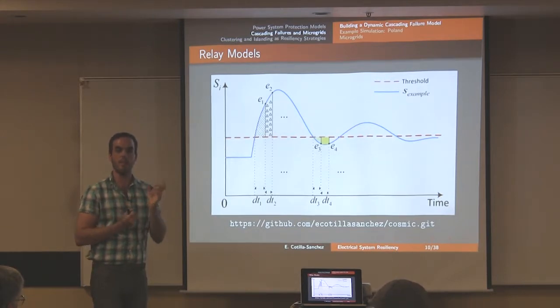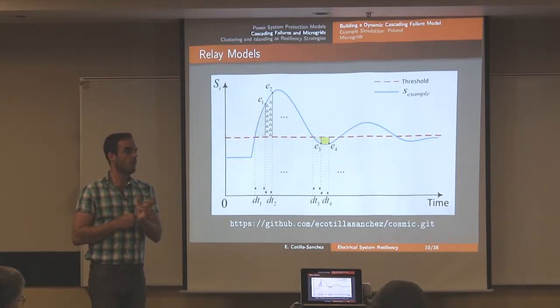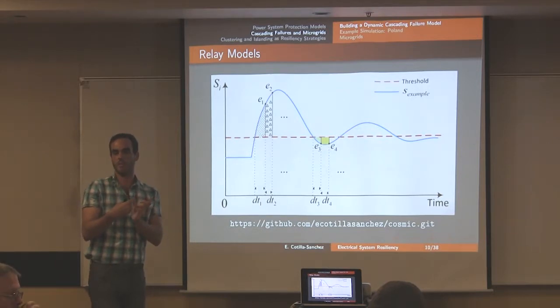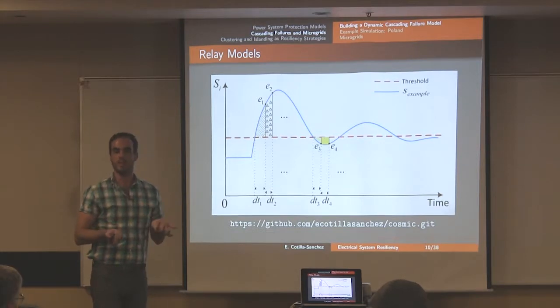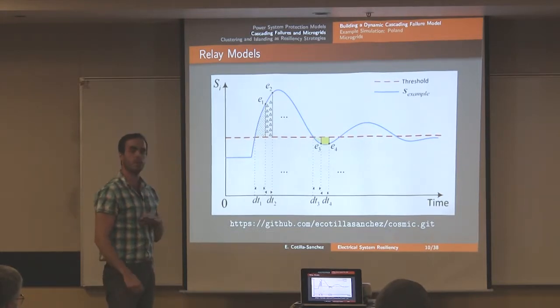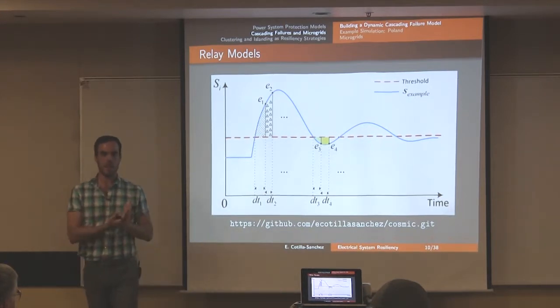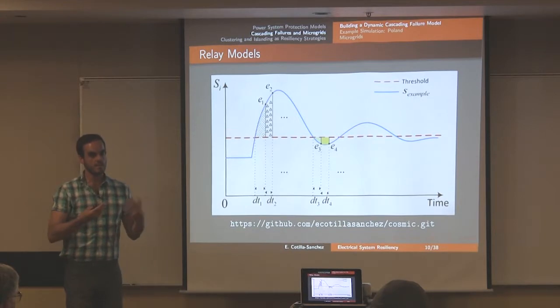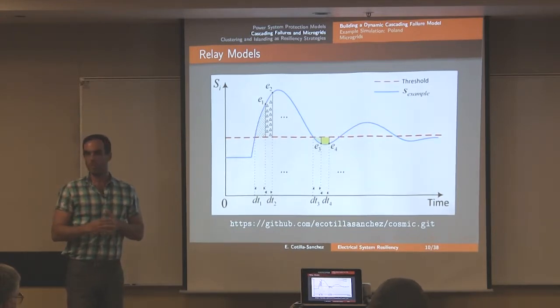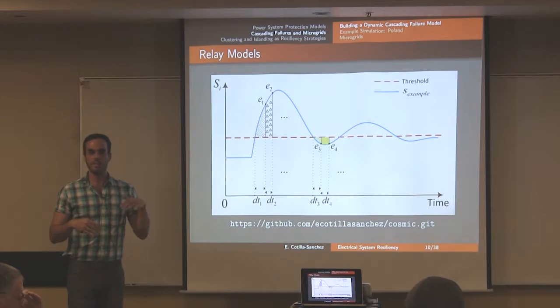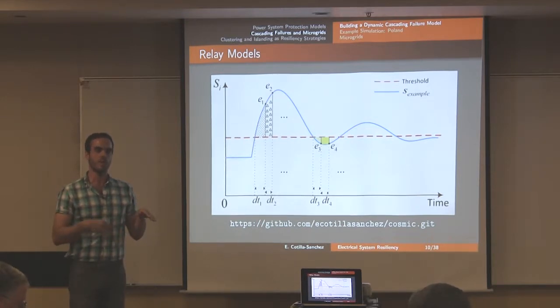So in this case, if you have a fixed step size, that's very limiting for relays that could trip anytime. Then you need to go back and see what actually happened in reality between the time that the relay would have tripped and the next time that you decided to solve your equation. The way that we address that in our simulator was to use a variable step size. If things are happening, we slow down and integrate all that my relays are doing. If things are flat and there's nothing interesting, we speed through so that we can gain some time, because time domain simulation is very expensive.